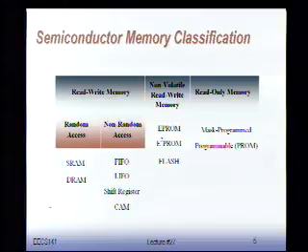Cross-coupled inverters. So SRAM is static, which means that if I keep the voltage intact, my data will remain stored in the cell. I don't have to do anything. I write something in an SRAM cell, I keep the supply voltages on, and it's going to stay there. If I remove the supply voltage, obviously I'm going to lose the value. Okay? DRAM is based on capacitance, which means it leaks. You store an amount of charge on the capacitor. That's a 1. No charge is a 0.